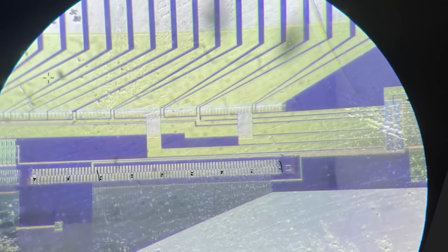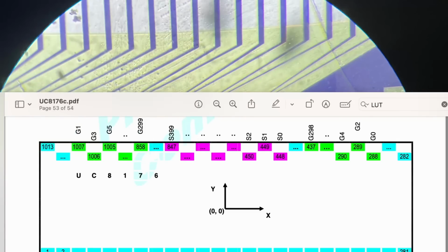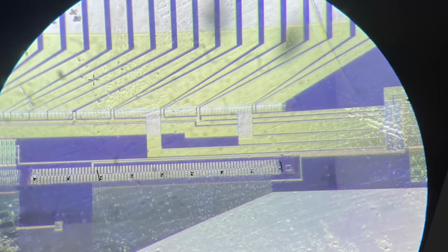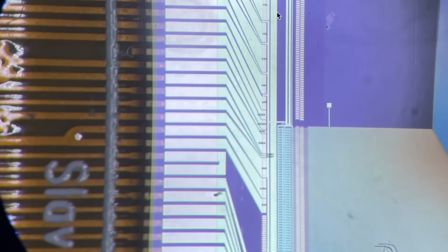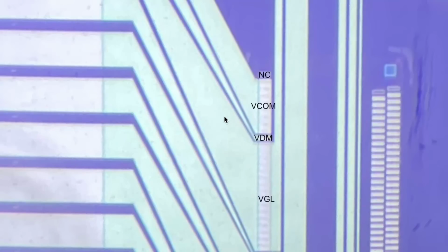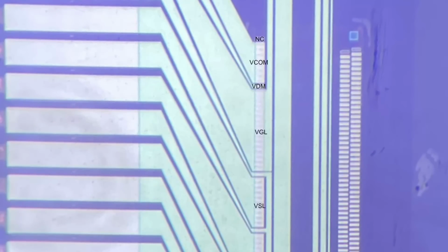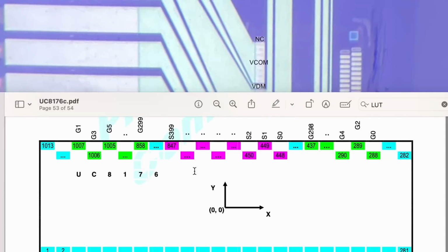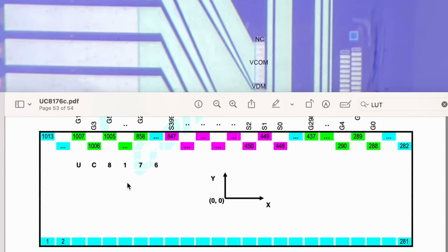So now if I take more photos, zoomed in on these sides, around that edge, and then correspond that to the datasheet, I should be able to derive the pinout. So yes, here it is. I have another photo taken on the other side of this chip. I already labeled these, but I will show you how it's been done. This view is this view rotated 90 degrees, so we know this pin is actually pin 1.